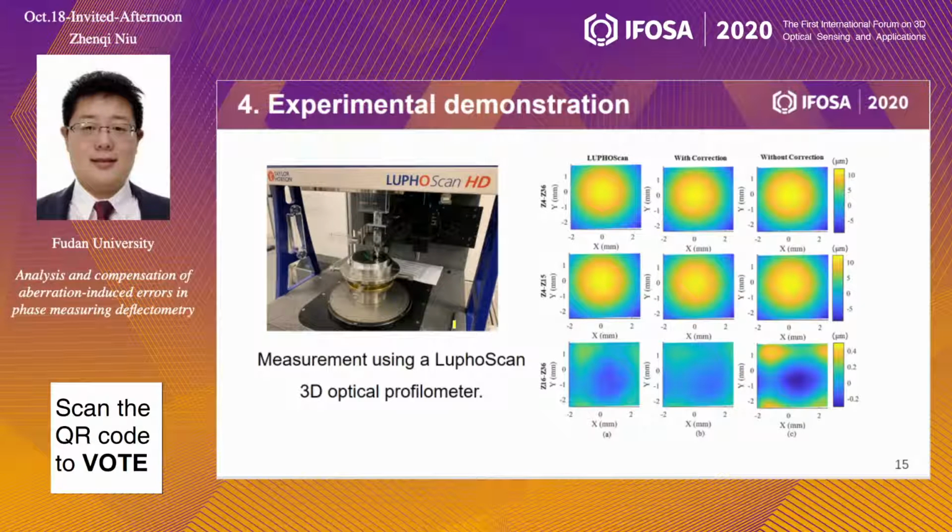The measurement results are fitted using the first 36 terms of the Zernike polynomials. The piston and the tilt, corresponding to standard Zernike terms 1 to 3, are removed because they are relevant to the pose of the workpiece rather than the form.